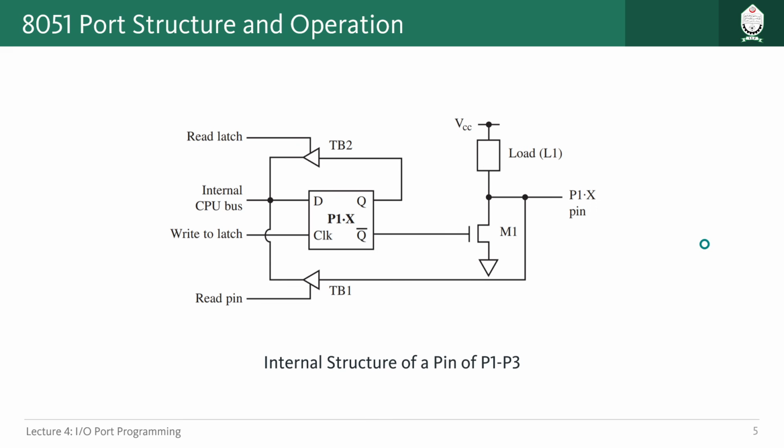Okay, so now a very important topic for this lecture: we will try to understand internally how the pins of microcontroller ports, or 8051 ports, are built, and how these pins can be used as output or input. Let us first start with output.